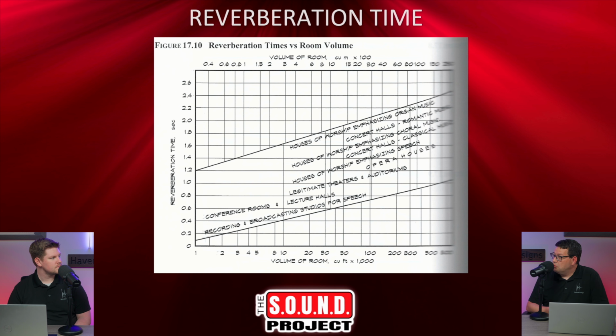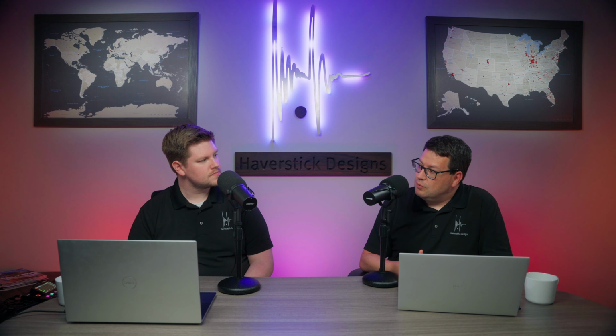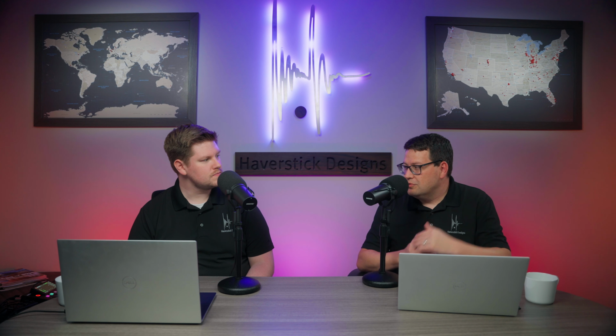Sometimes even up to 2.8, 2.9, like Vienna and the Concertgebouw in Amsterdam and Boston Symphony Hall. All these have a really long reverb time, but if you try to use it just for speech only, it'd be very hard to understand what someone is speaking in a room with a 2.5 second reverb time. Because for speech, it might be more around 1 second or 1.5 seconds. And so there's a big difference when you compare those two reverb times.